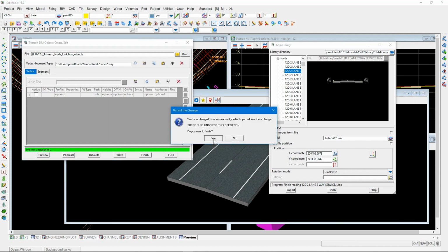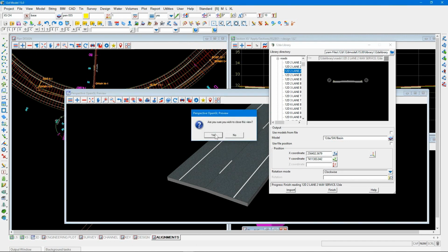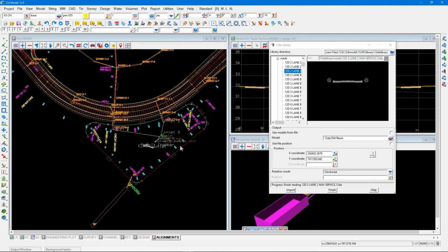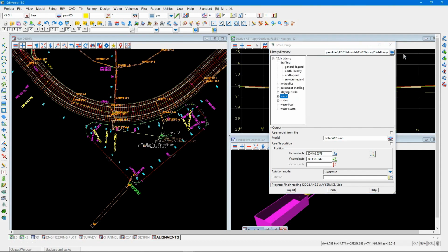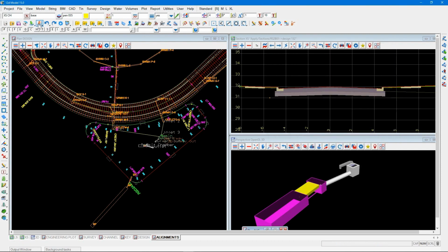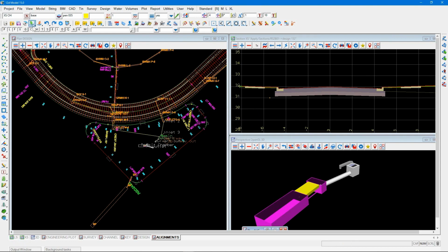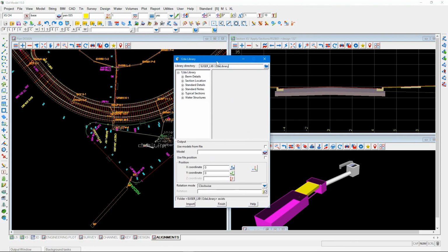And of course, if I wanted to insert many of them, I would be using these BIM objects create options inside 12D rather than just importing them singularly. But you can do it whichever way that you want. So I've got an item here in my 12DA library, and it's from my user library, so I'm just going to reselect that. Actually, I'll show you where you can get that as well from the quick access toolbar, from the data input toolbar, the 12DA library item, and that's just accessing it from a toolbar rather than accessing it from the menu item itself.